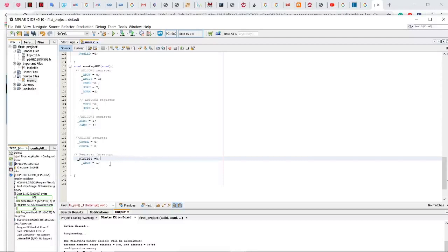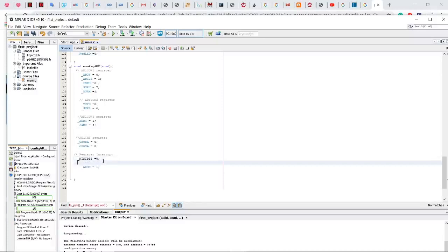equal to 0, because if we are going to activate that bit, what it means is that an interrupt can go within another interrupt. It can cause a mess in your code. You need to be very, very sure that you know how you can handle that configuration. But in our case, we don't need to do that. We are just going to simply set up the interrupt configuration.